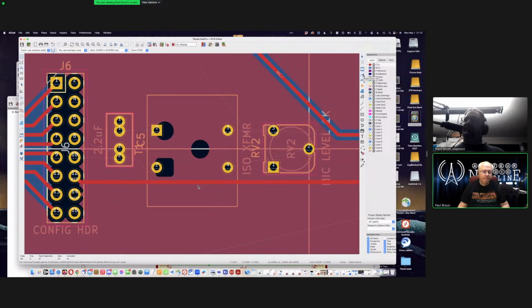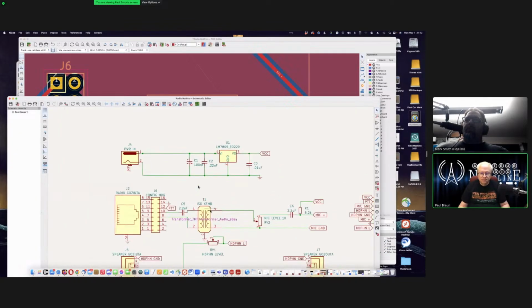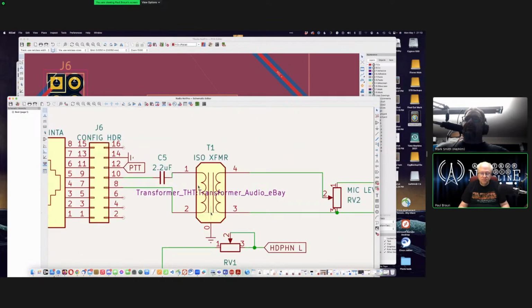So, remember when I said phase doesn't actually matter? Yes. Let's put that to the test. Because right now, pin 2 to 8 has to go underneath that capacitor, which we kind of don't want it to do. So what I'd like to do is go to your schematic and swap the wires going into pins 1 and 2, which means on the schematic, they're going to cross each other.